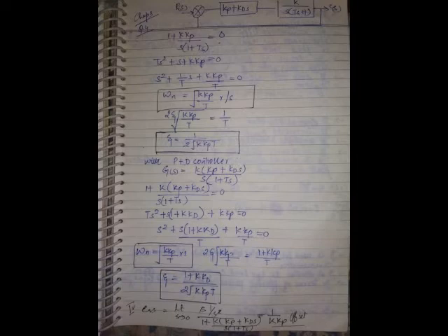So we have (Ve minus V1) by R1 by (R1 CS plus 1) equal to (V1 minus Vout) by R. So minus Vout will become Ve into (R1 CS plus 1) into R2 by R. This will become R2 by R1 into Ve plus R2 by R1 into R1C s Ve.